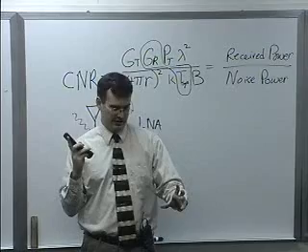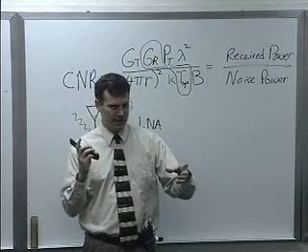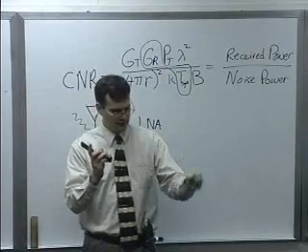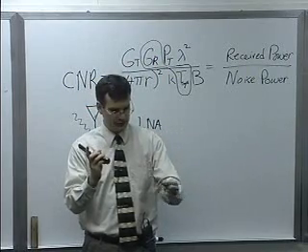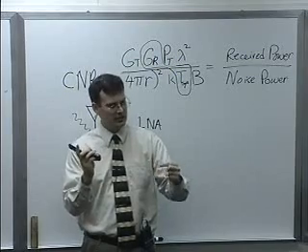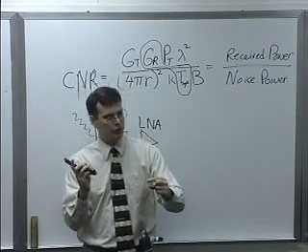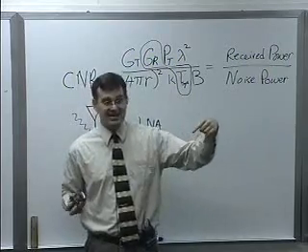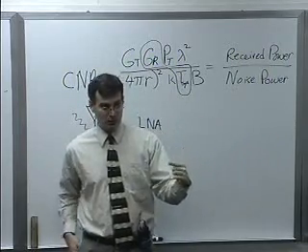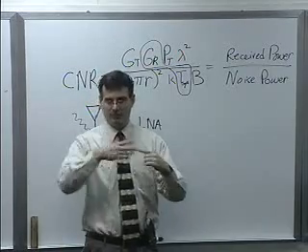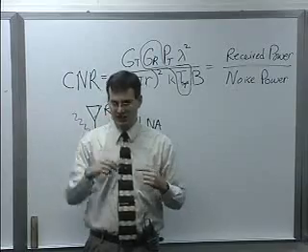So even if I lose some signal energy from the cell phone through the antenna and through some of the devices, when that really strong signal hits that first amplifier, it could drive it nonlinear. And once that LNA goes nonlinear, any desired in-band signal that you put through there is going to get severely distorted and clipped. And you're probably going to lose it completely through your chain.